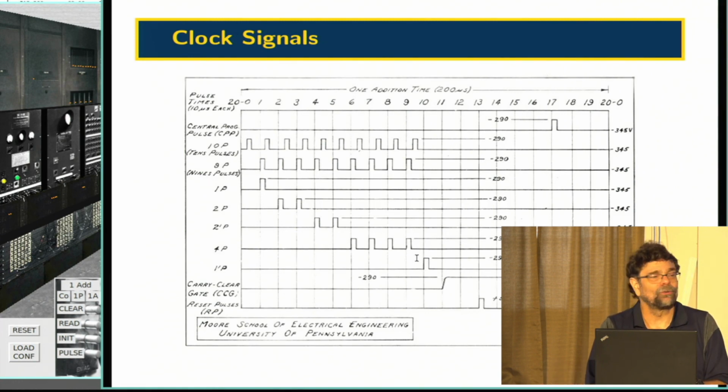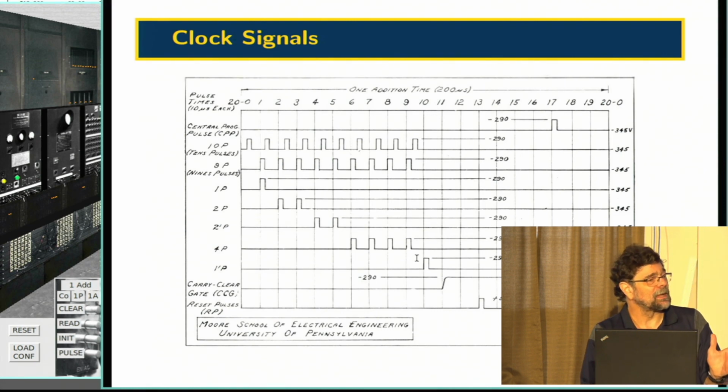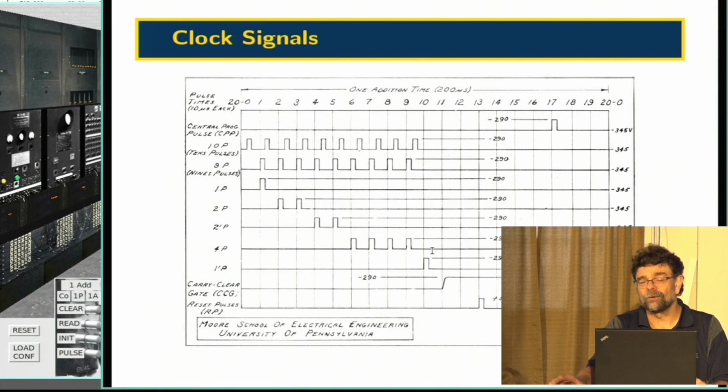And that is to have that one extra thing that you add when you're doing 10's complement. Think back to your 2's complement lessons. It's 1's complement and you add 1. 10's complement's the same way. It's 9's complement and you add 1. This little pulse right here is the add 1.